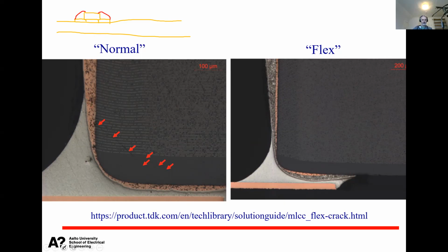So typically, maybe I will use light blue, the solder interconnections with the ceramic capacitors are something like this. As you can see from these images, this is the copper pad. The solder, this one, is not going up here. It's just quite a small amount of solder here. And the same with this one.